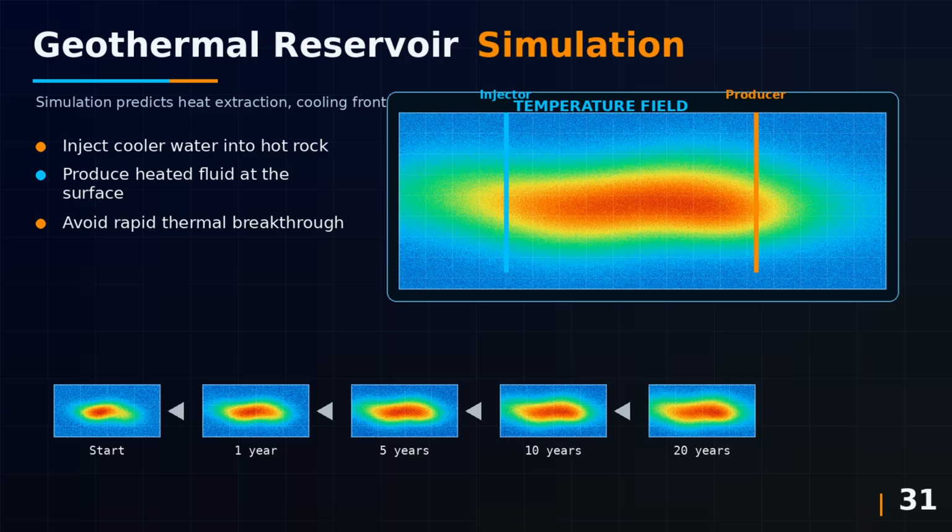Geothermal simulation also connects strongly with geomechanics. Cooling can change stress, potentially inducing fractures or seismicity. Pressure changes from injection and production also influence the stress field. This means modern geothermal simulation may require coupled thermal, hydraulic, mechanical, and sometimes chemical modeling. The broad lesson is that reservoir simulation is not limited to oil and gas. It is a foundation for many clean energy subsurface technologies.